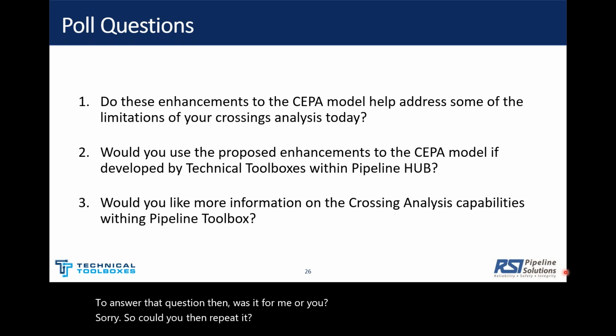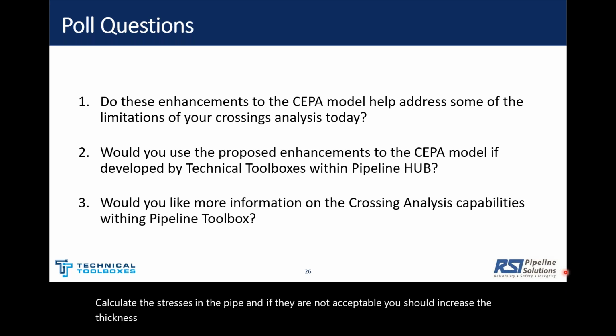It was a question of, can the model prescribe or calculate a minimum thickness for steel plates or timber mats to achieve a designated load limit? Not directly. The way it works is that you need to enter the properties that you want and let the program calculate the stresses in the pipe. And if they are not acceptable, you should increase the thickness until it's acceptable.